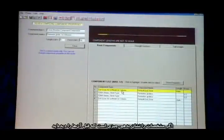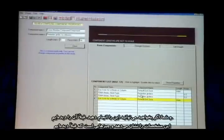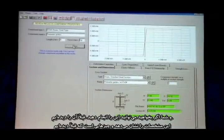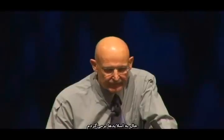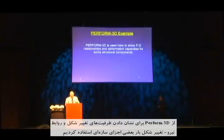If I show the properties, this is stuff we were looking at before. It's got an end zone, it's got a couple of basic plastic hinge components and another end zone. And if you want to, you can drill further down. We've already seen this, show the properties of this one, and this is stuff that we looked at before. That's just in a review mode. So that then is assigning the component to an element. I'm going to go back now to the PowerPoint. So we just did that, and we used Perform 3D to show deformation capacities, FD relationships from structural components.